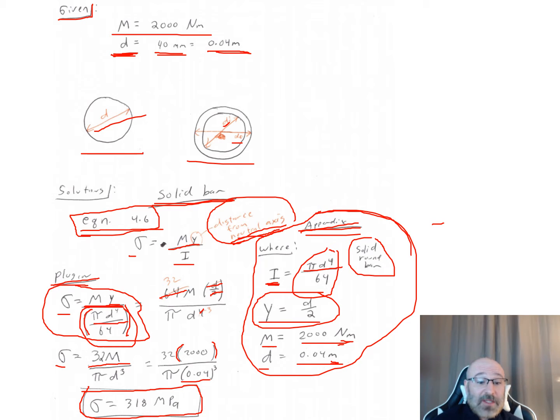And we wanted to say, well, what is the minimum diameter that we could do to be within that range to get our stresses according to our specifications. So that's one right there where we could write a little program that runs it through, and maybe we do diameters every 1/10 of an inch, every millimeter, whatever it is, and we run it through a range of those, and we say, oh, okay, now I'm looking at this, and then I have a whole chart I can look at. Okay, for these diameters, these are my stresses. So I can look at it and say, oh, okay, well, between this diameter and this diameter is actually going to be good for my design process.